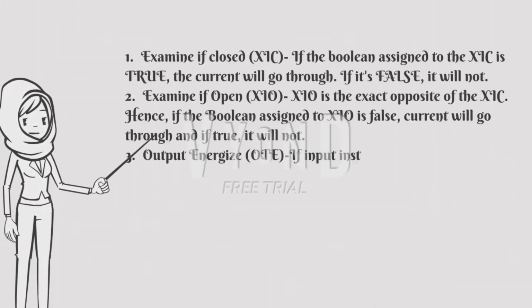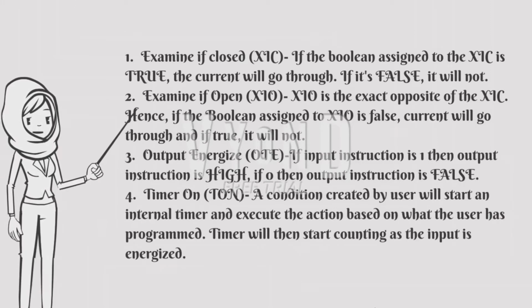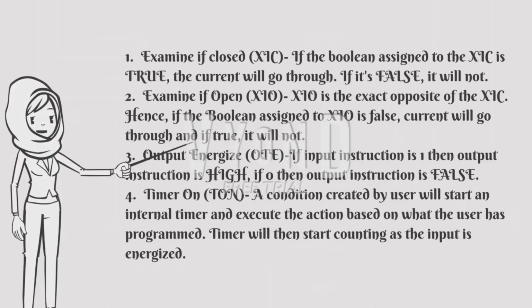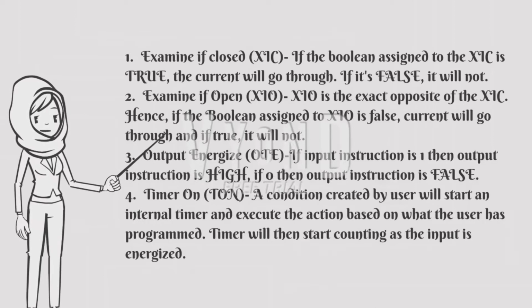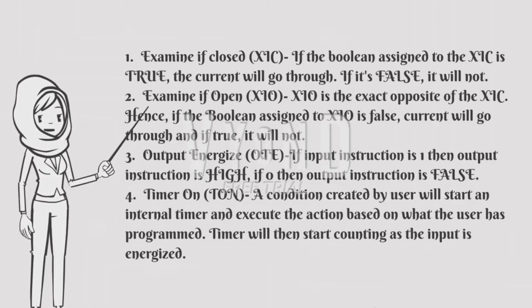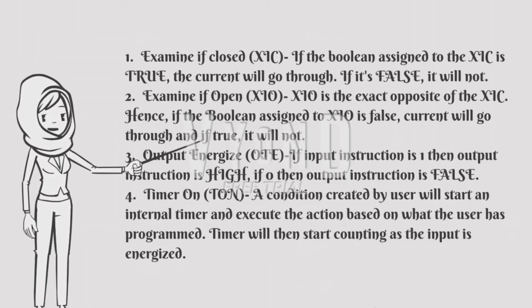In order for one to understand the ladder logic diagram, documentation is necessary. Documentation is the process of naming all the inputs and outputs as well as numbering all the wires, and this is for the purpose of easy referencing.